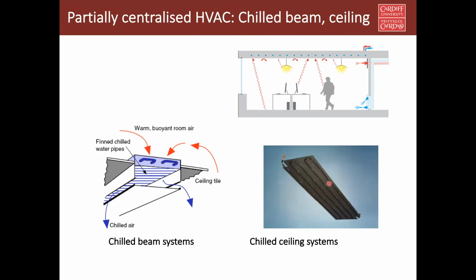Now, what is the difference from fan coil? In a chilled ceiling or chilled beam, the temperature is around 10 degrees Celsius, so they don't condense water, so they don't work as a dehumidifier, meaning that they don't deal with latent load. So latent load has to be dealt with by a DOAS, that is a direct outside air system. Okay, so that's the difference between fan coil and chilled beam. So chilled beams are a reasonably slow response system compared to fan coil system.